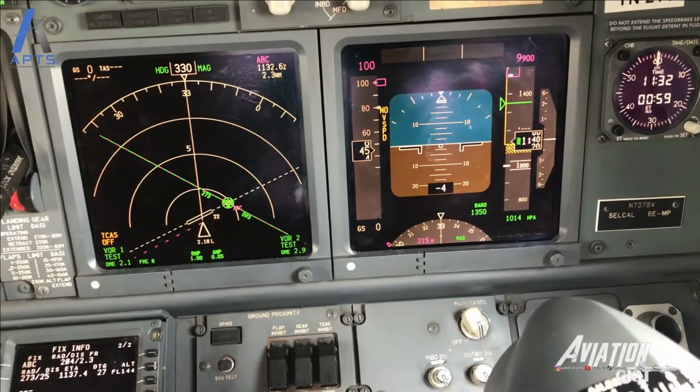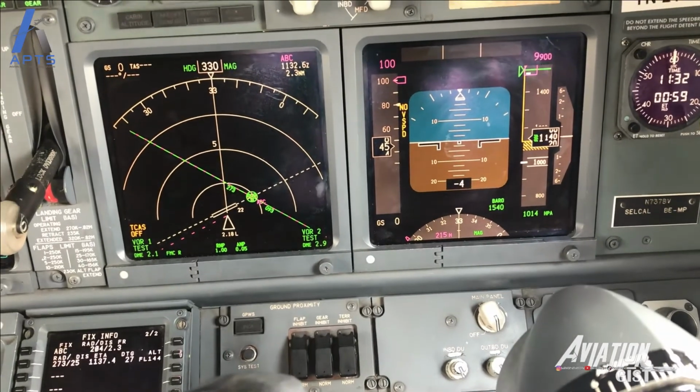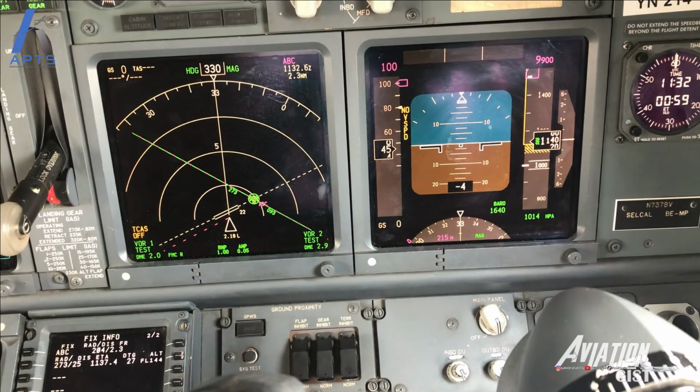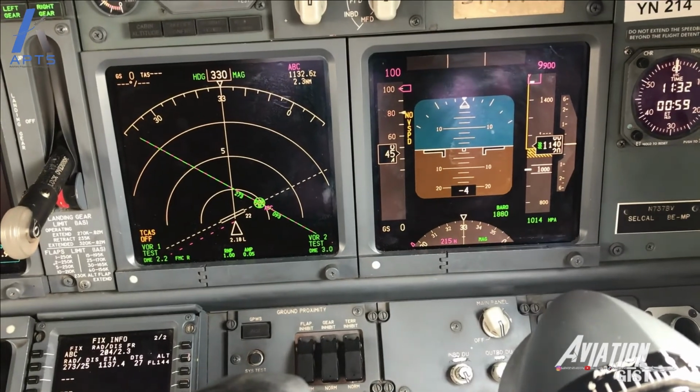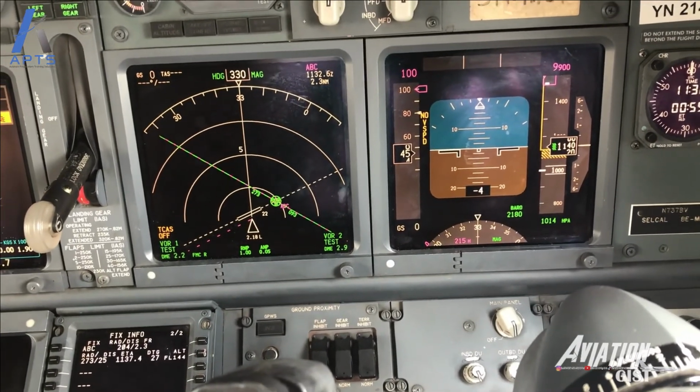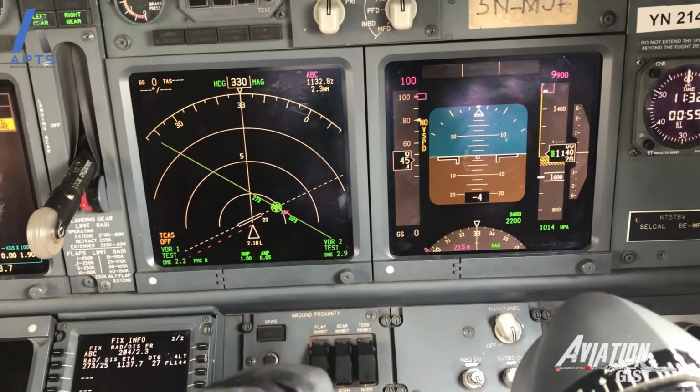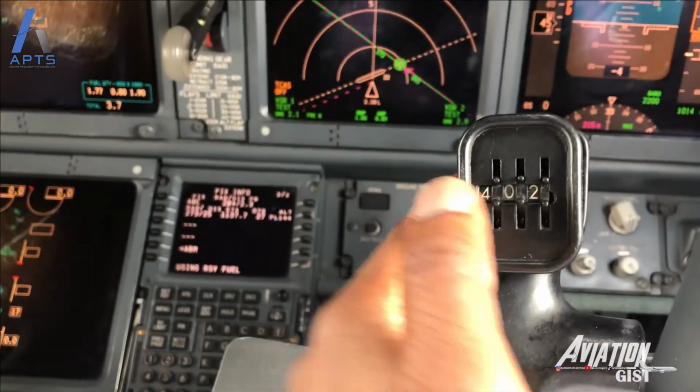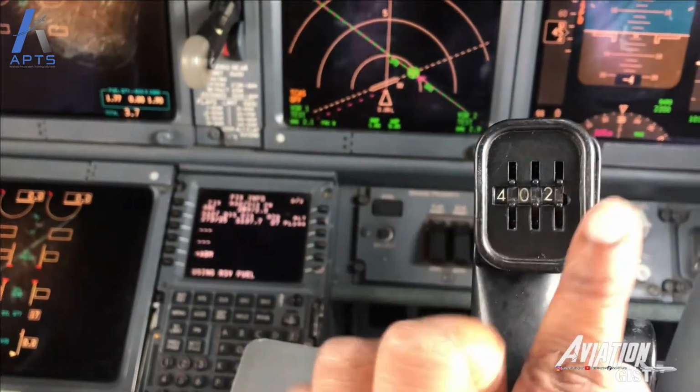Now that the initial preflight of the FMC is completed, you can set the minimum flap retraction altitude, MFRA, using the Baro selector on the FS panel. The MFRA in this case is 1,000 feet above aerodrome level, and in this case this would be 2,200 feet set. Check that you have set your flight number on the control column or yoke as it relates to the flight and verified from the OFP.